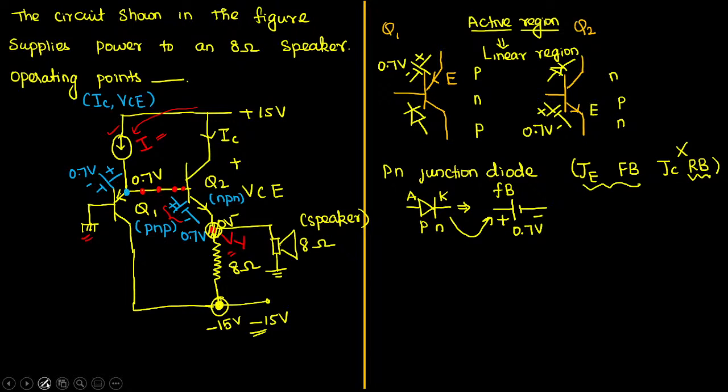Yes sir. Now how will you identify the current flow? See, now it's time to explore everything. What we are going to explore now is we are going to identify the current flow through this branch. It is very easy to identify it. Yes, that is what we are going to do now, and from this, we will explore other things further. We need to know the value of collector current and collector to emitter voltage only. So whatever the data that is given, I'm just trying to figure it out with the way that is given.